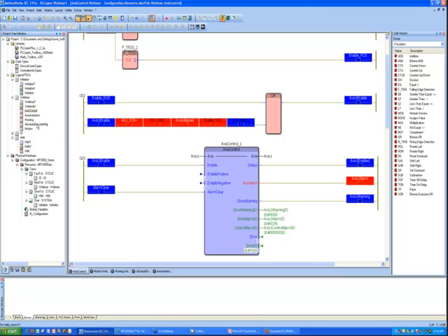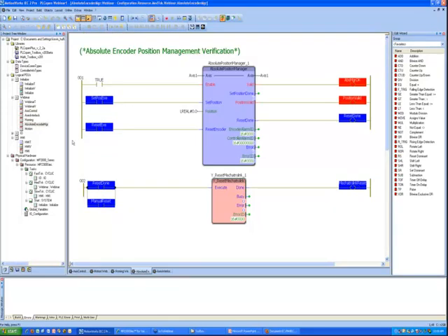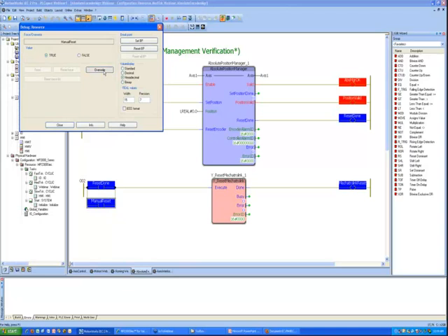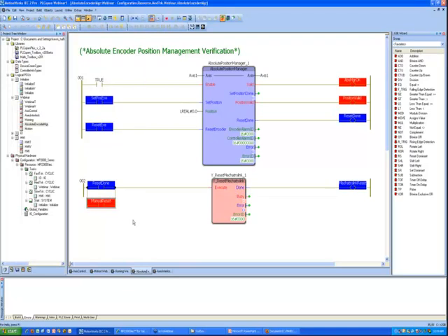In addition to that, we can actually clear it via software by resetting Mechatrolink, because that causes a soft reboot of the servo packs. So if I reset the Mechatrolink, the AC9 alarm will disappear. It did disappear, and now that the amplifier has restarted, we've lost our position valid output.